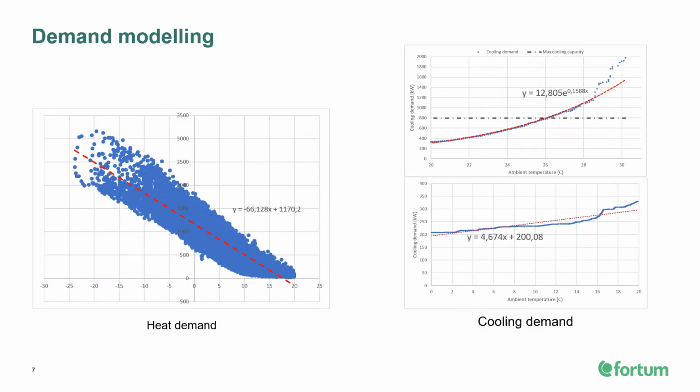So the heat demand was modeled based on existing consumption data from the consumption points. Since the buildings are existing customers of Fortum, we have existing hourly data on the demand of heat for each building. So they were just summed up together and then matched with data on the outside temperature from each time. Then a simple linear regression line was created, creating a heat demand function.